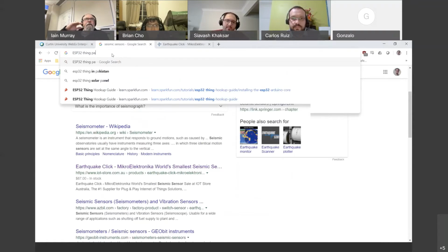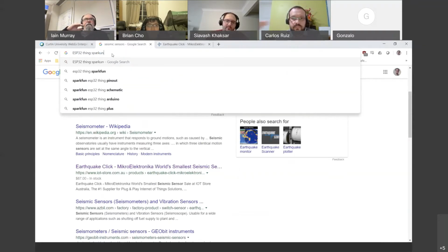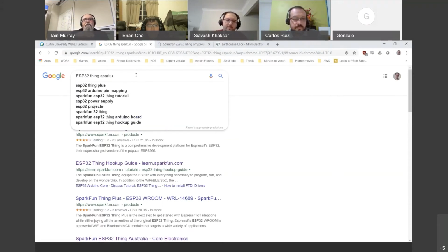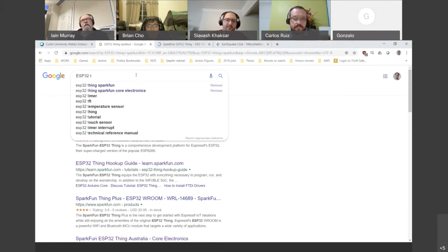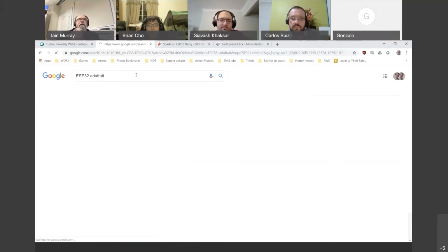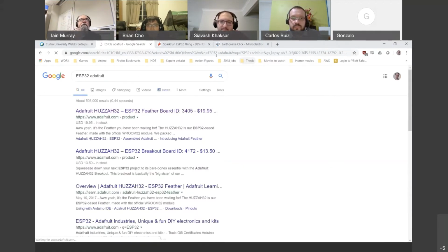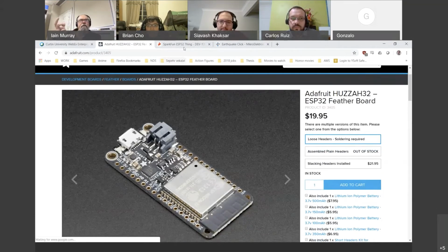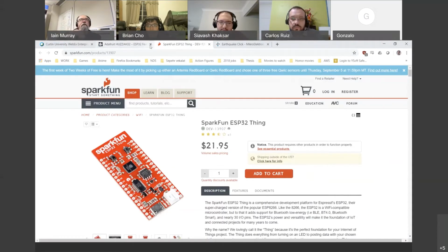We would have a level that we would need to be able to pick up if the vehicle was close enough, so the horn's loud. If it's quiet, we just ignore it, too far away. And we could actually detect set frequencies that are used within the horn range. Where it falls down, of course, is if people add aftermarket horns and they don't match the frequency. But using a microphone array, we would pick up the direction of the sound, so we could alert a deaf driver that there is a horn sounding at the left front of the car.